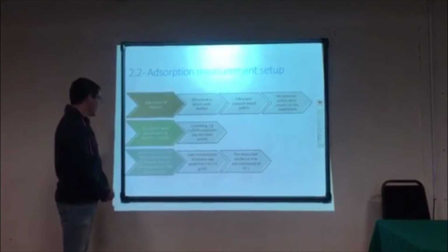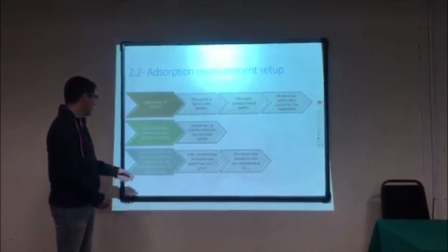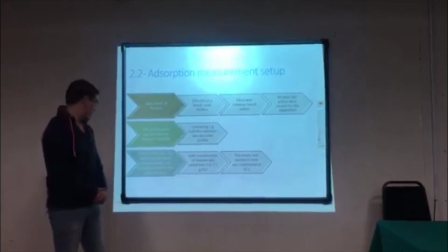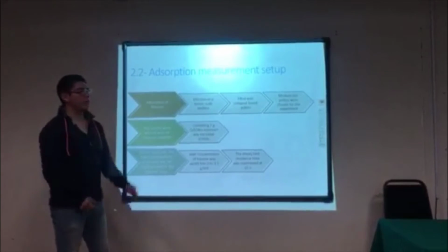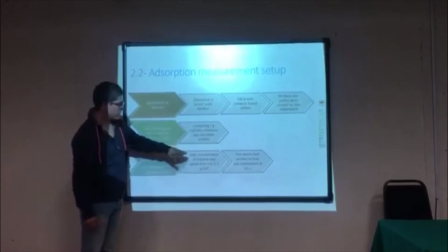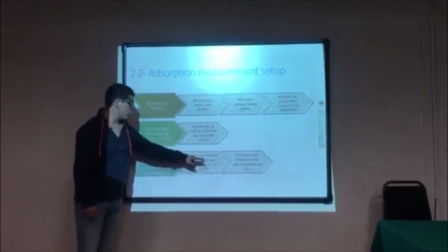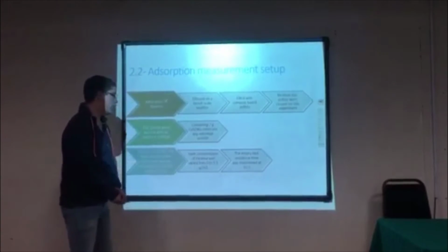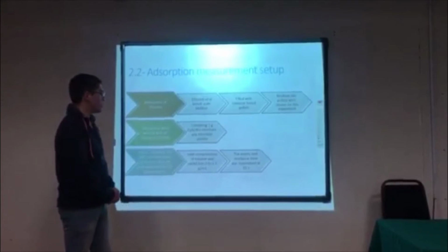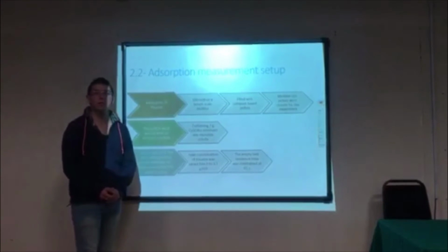Then, before each test, the inlet concentration of toluene was set and measured at the desired value. The desired inlet concentrations of toluene ranged from 0 to 3.1 grams per cubic meter, and the empty bed residence time was 65 seconds.